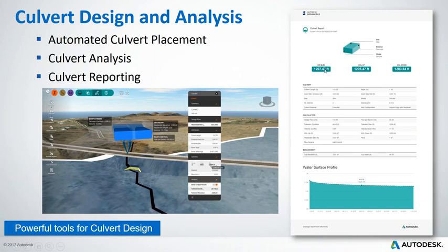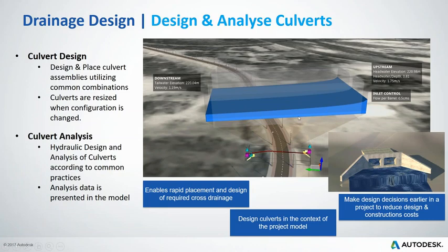It showcases the high level elevation, the hydraulic grade line in the up and down. And as you can see, you have everything in terms of the culvert parameters, like the length, the size, the number of barrels, the type of those barrels, whether they are squarish or rectangular or circular, and other parameters as well that were used to calculate the flow from the top to the very bottom of this culvert. So this is another representation of how the culvert will look. Once you highlight and pick the analysis icon, you see all of the parameters.